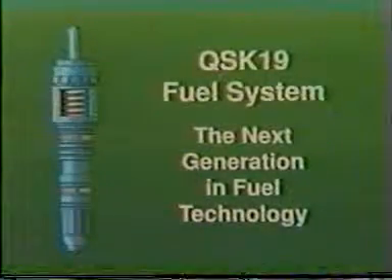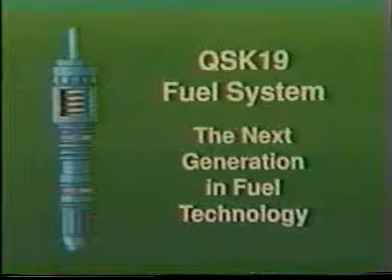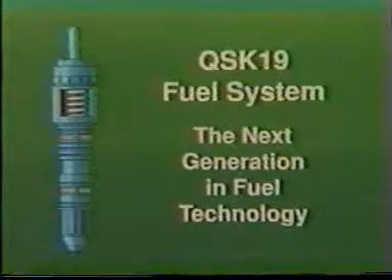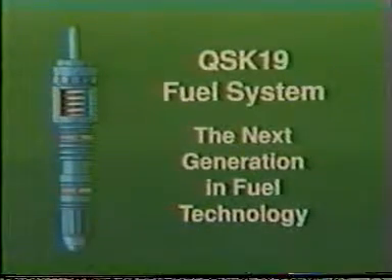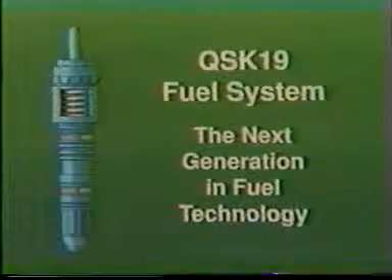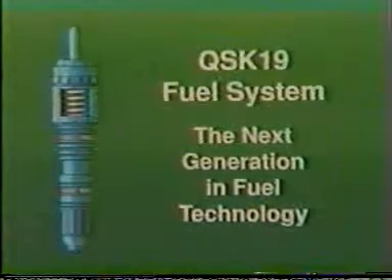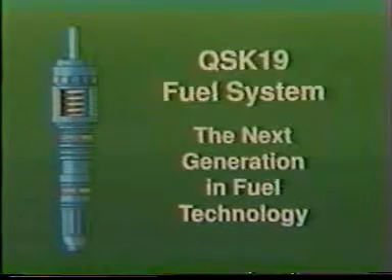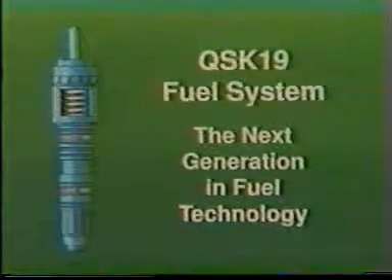The QSK-19 fuel system injector shares many design features with PT and Select. It represents, however, the next generation in technology. The new QSK-19 fuel system injector will be capable of up to 35,000 psi of fuel injection pressure in the future. Currently, pressures are in the 25,000 psi range.